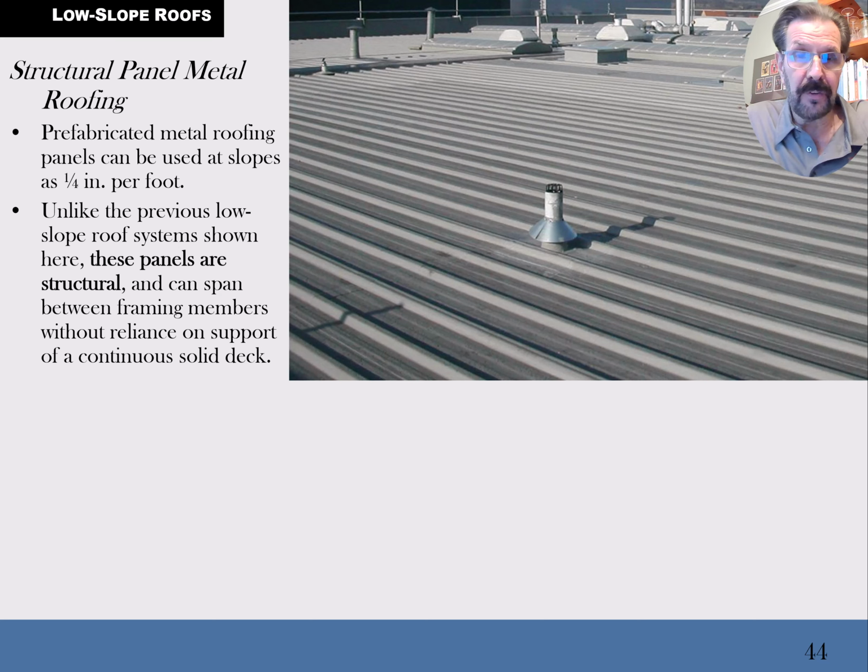If a garage door is left open, or if the garage door isn't strong enough to withstand the wind blowing against the side of the building, it can blow in that garage door, and then it inflates the building and takes that whole roof off really easily. So those are problems with windstorms, and then problems if it's not installed well at the edges so that the wind cannot catch it is what you need to worry about, making sure. But this stuff can generally be kept down to as low as a 1/4 inch per foot slope. So when we start looking at really gentle slopes like that, the sheet metal roof is a good candidate for that.